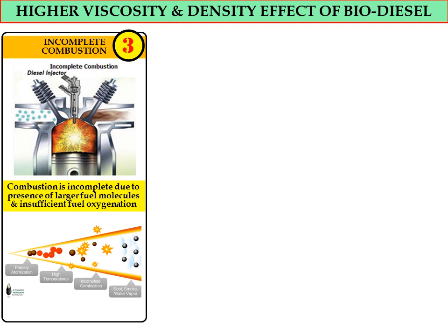The second figure shows the combustion process. First we have primary atomization, where the fuel will spray thousands of small droplets into the combustion chamber. Then in the second process, due to the high temperature and pressure, the fuel droplets will combust. However, part of the droplets still do not combust due to the incomplete combustion. Then, due to the incomplete combustion, the process will produce soot, the black carbon particles, and also smoke, plus water vapor, which is the side product of the combustion process.